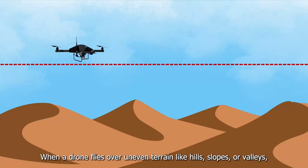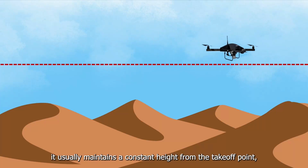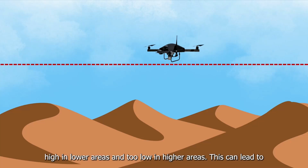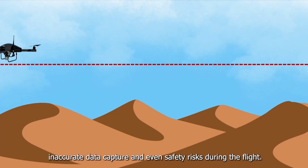When a drone flies over uneven terrain like hills, slopes, or valleys, it usually maintains a constant height from the takeoff point, not from the ground. Because of this, the drone can sometimes fly too high in lower areas and too low in higher areas. This can lead to inaccurate data capture and even safety risks during the flight.